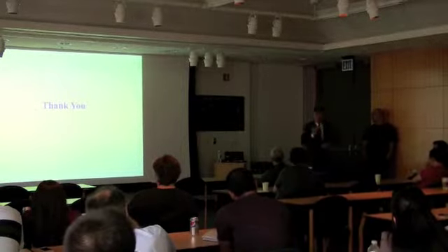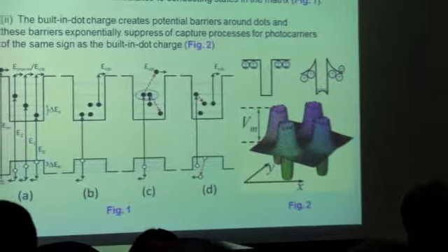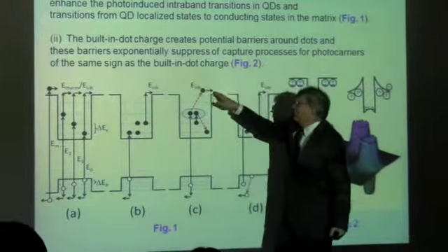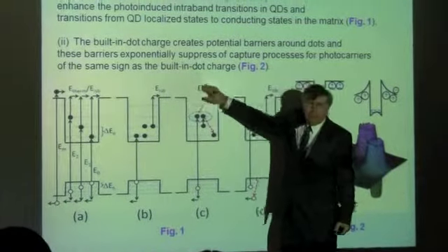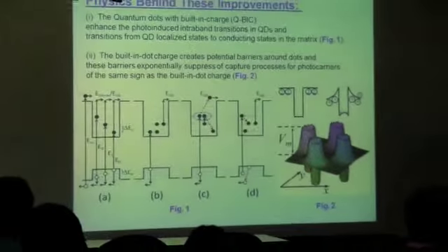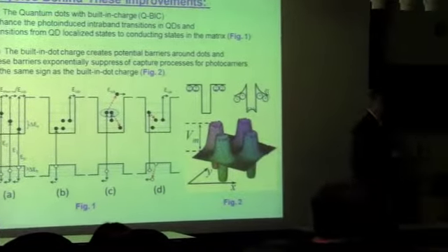The advantage of germanium and silicon is that, if I go fast to the slide that I showed you before about the band structure, there is a small discontinuity for holes. The following will happen: electrons in germanium have this barrier, so electrons would never be captured in the dots. For holes, there is a potential depth.